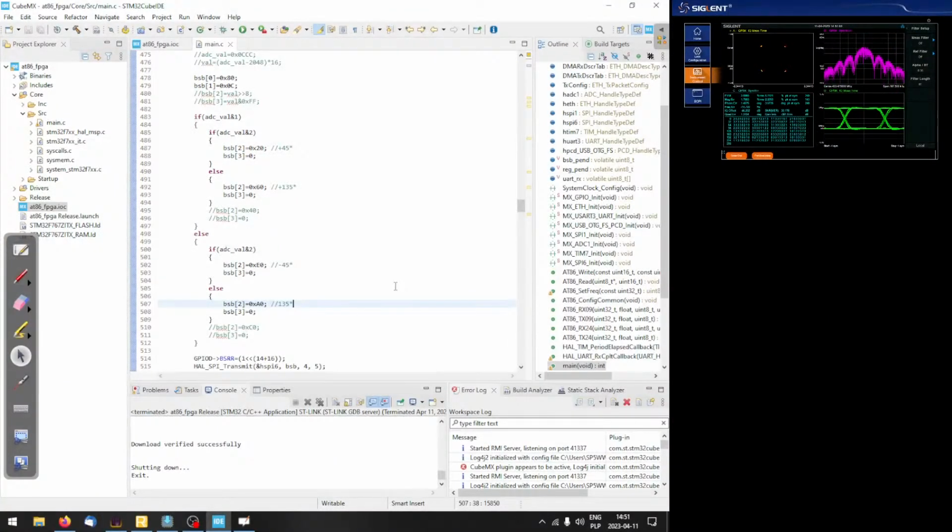That's 30 dB for the MER. Yeah, so if that stuff works, the next step would be to filter the baseband, probably also try with the differential PSK, and maybe also with the pi/4 DQPSK that is used in TETRA. And probably that's it. So the problem was between the keyboard and the chair.